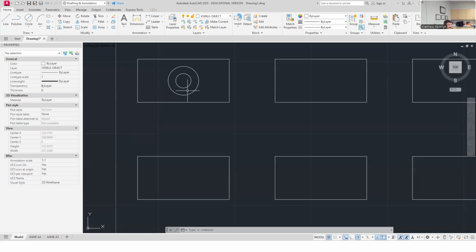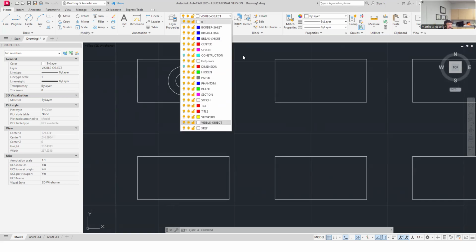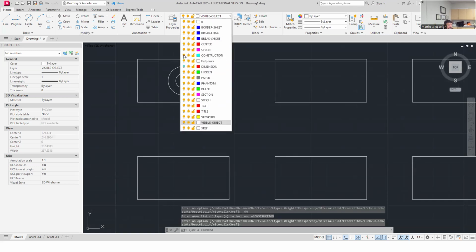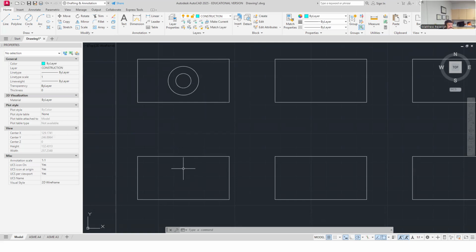It's hard to tell what's going on in just a top view, but how orthographic projection works, and will continue to work for quite a few weeks now in our drawings, is that we don't have to draw these as 2 independent drawings. I use one drawing, and this is the principle of orthographic projection: I can just use the details I've done in one view to project those to the other view, right? And so this is my systematic approach to that.